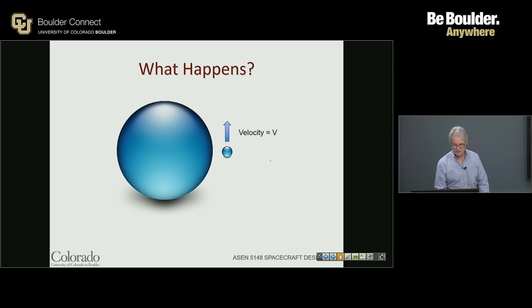And when I say radius, what I mean is radius from the center of the planet to the object. In some problem statements in Brown, you're given a height above the planet. Keep in mind that the radius is always to the center of the planet. In the case of the Earth, we've got to add 6378 kilometers to the altitude that the spacecraft is at to give us the overall radius to the center of the object.